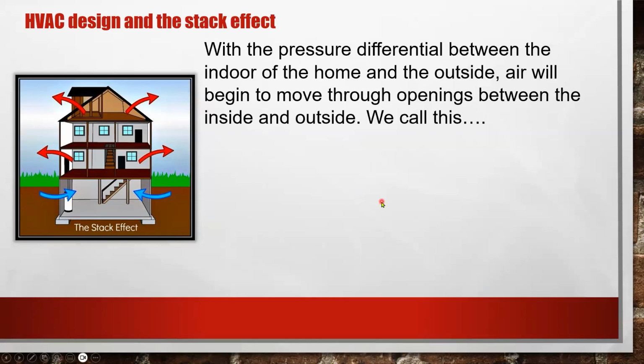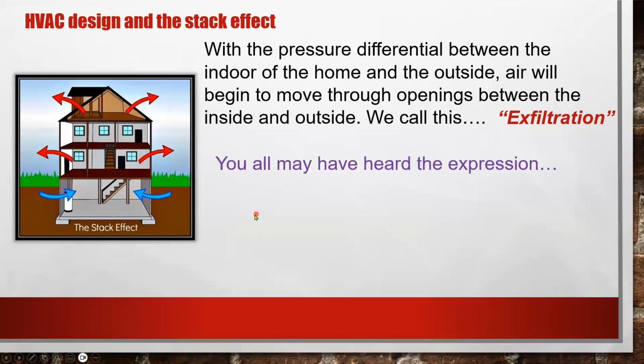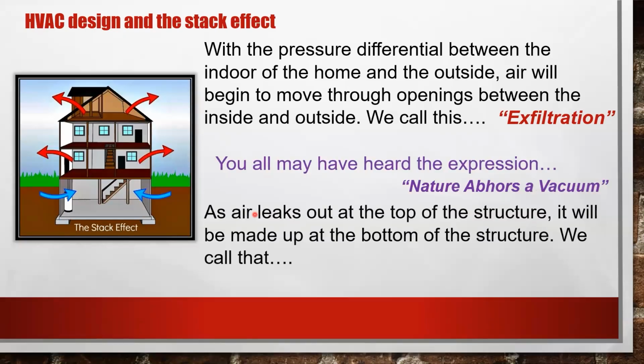When there is a pressure differential between the indoor of the home and the outside, the air will begin to move through any openings between the inside and outside. We call this exfiltration. And you've all heard the expression, probably, nature abhors a vacuum. We cannot exfiltrate without also infiltrating to make up that loss.